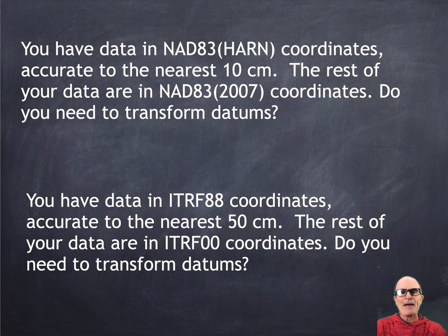They're not going to be mapped at a resolution better than what the datum transformation is going to move things. So it's saying, look, I don't know where anything is to the nearest 5 meters, 15 feet, and yet you wanted me to do this whole processing step that shifts things 8 inches? I don't think that makes any sense, or 4 inches or 6 or whatever the small amount is.